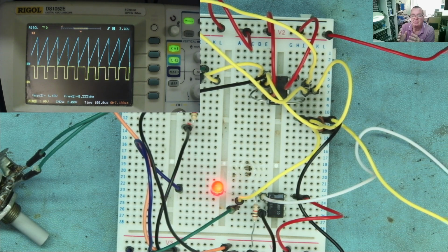If the MOSFET goes short from drain to source but not to the gate, your controller chip which is connected to the gate may be just fine. If the whole thing has gone short, it's possible that a lot of high voltage went straight into the pulse width modulator controller, usually an IC, and caused it to blow. So really that again brings us back to the output devices normally cause the problems in PWM circuits.